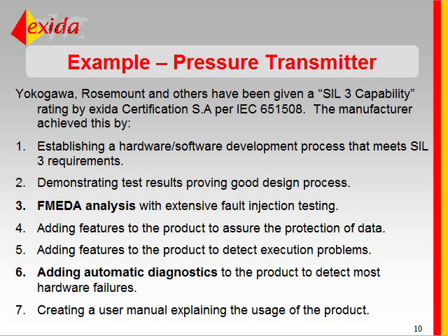Number one, it helps demonstrate compliance to many of the requirements of the standard, but perhaps more importantly, it gives relatively accurate failure rate and failure mode data needed by system designers at the project level to actually design safety instrumented functions.